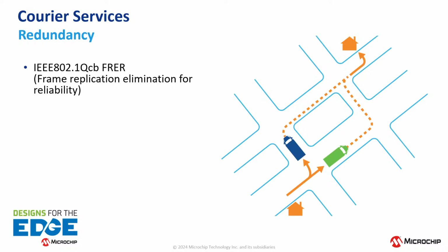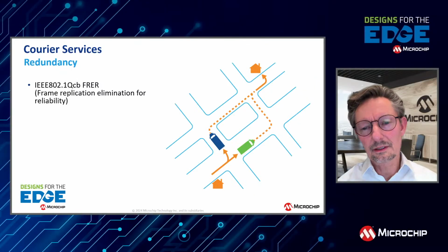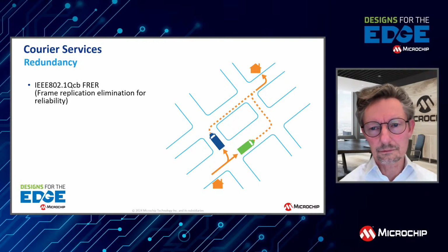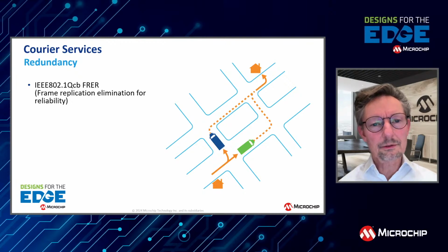It's very simple, very neat, and in my belief, this is the superset of redundancy. There is other legacy redundancy, there's PRP or HSR, which is ring topologies or parallel networking. So in this case, I would say that FRER is a superset because this is mesh-based, stream-based, where the other one is port-based, and this is much easier to work with. You can still run the legacy standards virtually together with this one. So this is not one or the other. You can use both of them if you like.